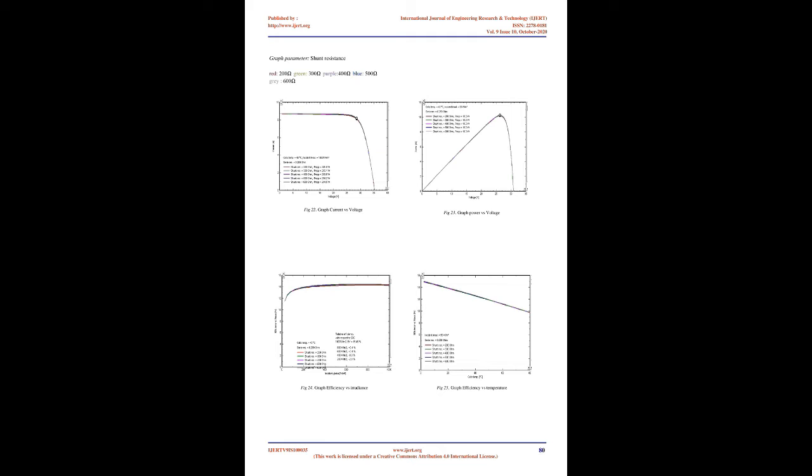R series is the internal series resistance of the one-diode model. It is one of the parameters of the model. At STC, it is not directly measurable using the I/V curve. Its determination is crucial, and has consequences on the low-light performances.